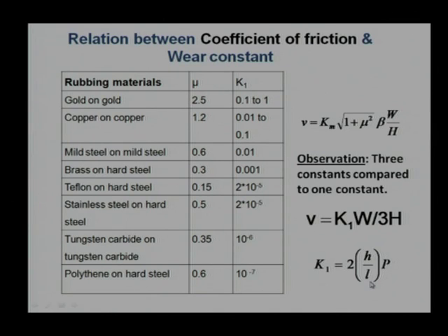So, that relation is valid for spherical asperities. Some modifications have been proposed by researchers. He said that instead of using a spherical shape, we can use any rectangular or other dimension, where the thickness of the asperities is given by h and the length of the asperity by L. Use this relation to quantify the wear equation, instead of writing K1 directly as a constant, write K1 in this term.